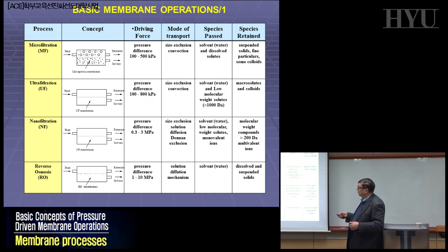In ultrafiltration, you still have a porous membrane, but the porosity is much smaller than the one you have in microfiltration. The other difference here is that normally the microfiltration membranes are always symmetric. You don't use asymmetric membranes here. You don't need to. The pores are big, and this is a way in which you can realize high flux also when there is suspended solid and similar.